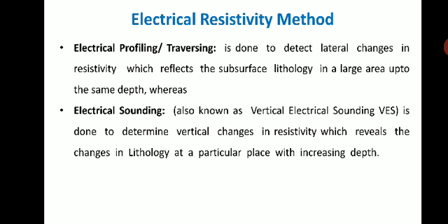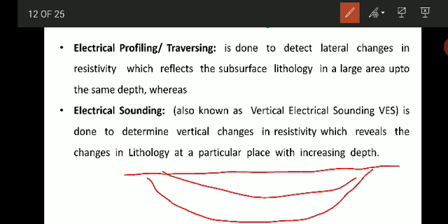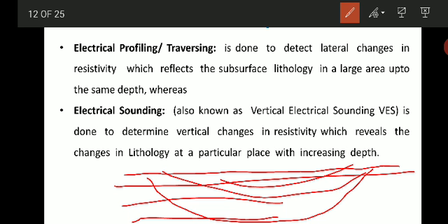Let's see what profiling and sounding are. Profiling is also called traversing. This is done to detect the lateral changes in the resistivity, which reflects the subsurface lithology in a large area up to the same depth. Suppose this is the ground level and you are sending current into the ground. Profiling detects the lateral changes in the resistivity, which reflects what is there in the subsurface lithology.